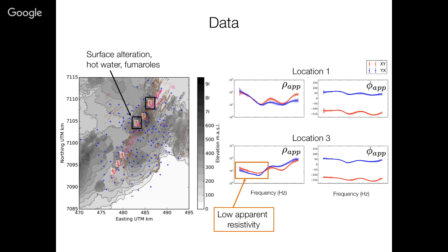And you can see, okay, we're going resistive. There's something conductive. We go more resistive, more conductive, resistive. So you can imagine that, at some scale, there's maybe 4 layers there to give rise to that. So that's this guy up here. If you go down to this point, then at location 3 here, we notice a couple of things. First of all, the overall resistivity has decreased by an order of magnitude.